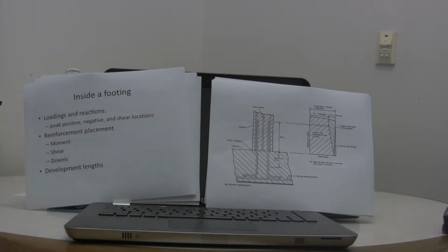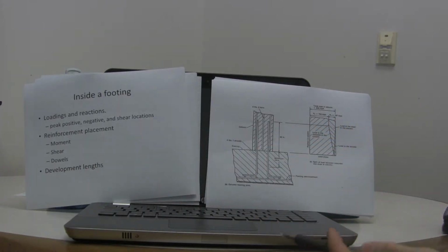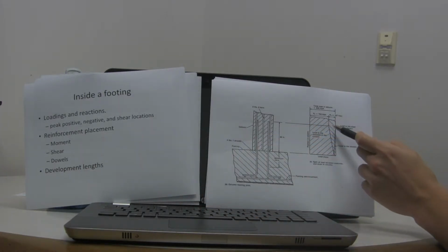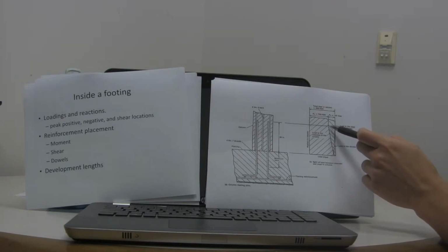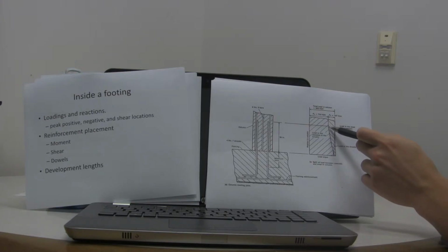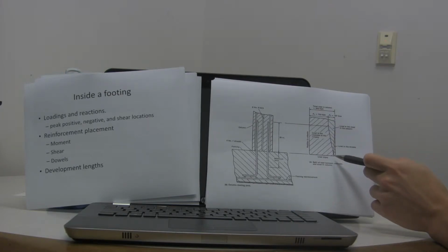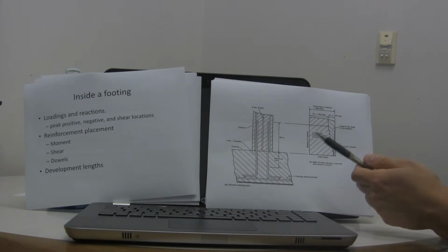After a footing has been designed, it is necessary to calculate development lengths with regards to detailing of these footings. In this diagram, one can see how the loading transfers from the concrete to the steel at the concrete and steel interface. Here, the height of the triangle is the length of the development length. And as the triangle gets smaller, one can see the load transferring from the concrete to the steel.